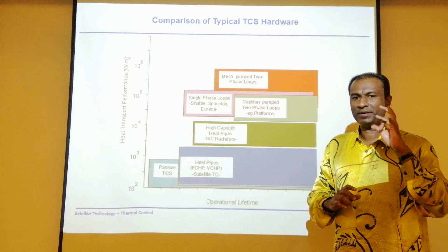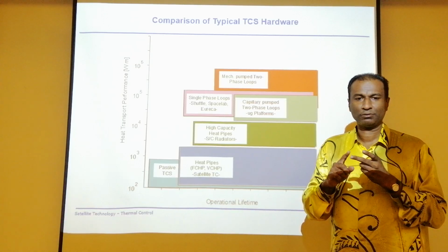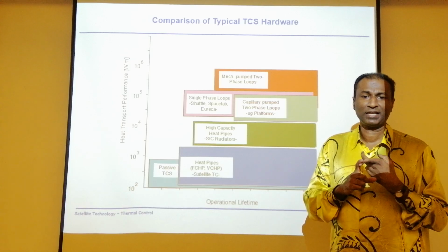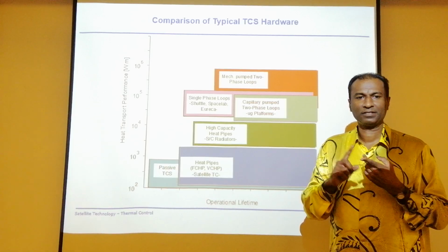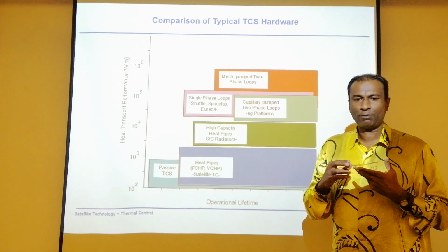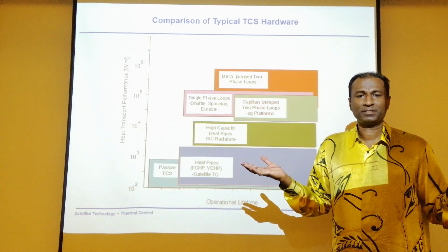There are two phenomena that we observe here. One is thanks to the capillary effects that we have. Another one is the typical surface tension. I think all of you have heard of the surface tension of a particular liquid. Both these effects complement each other to make sure the fluid flows. So there is no pump actually needed.